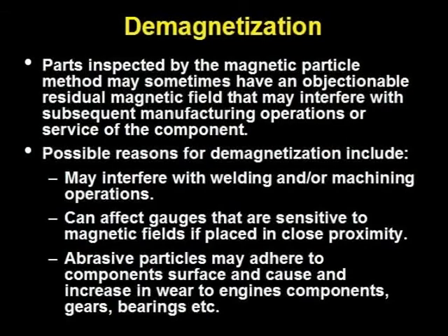Parts which have been magnetic particle inspected are usually demagnetized after inspection. The residual magnetism might interfere with welding or machining, affect gauges nearby, or attract abrasive particles, which would cause increased wear.